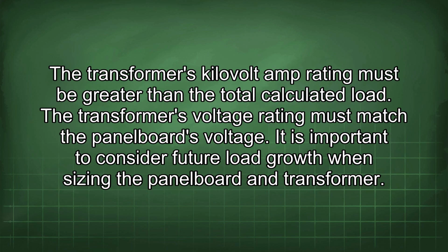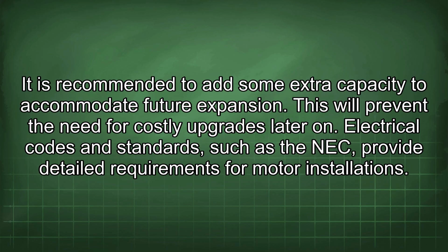The transformer's kilovolt amp rating must be greater than the total calculated load. The transformer's voltage rating must match the panel board's voltage. It is important to consider future load growth when sizing the panel board and transformer. It is recommended to add some extra capacity to accommodate future expansion. This will prevent the need for costly upgrades later on.